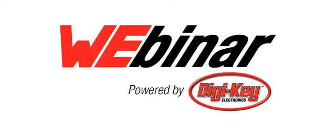Okay, I see another question here on the ULD rating slide. Why is the connector rated for 105 degrees Celsius? And this is quite easy. Remember the relative thermal index for our polyamide. This connector is made out of polyamide. It's a PA66 made connector, and therefore we have a relative thermal index of 125 degrees Celsius. Remember our security margin. This is the reason why we rate our connector for 105 degrees Celsius. Then we are always on the safe side.